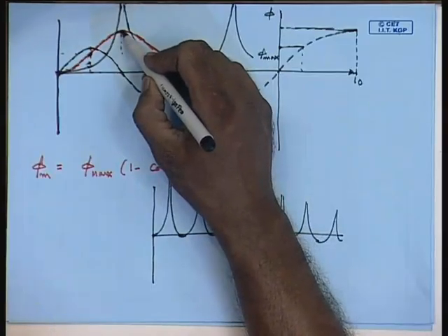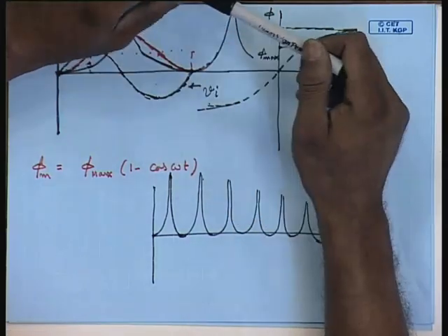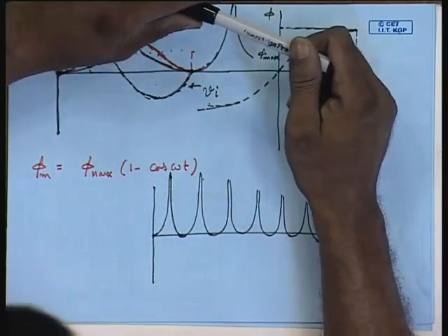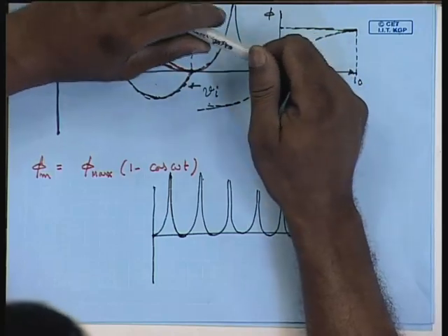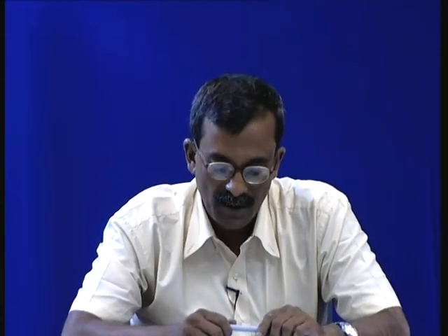So, if you have some remnant flux in the transformer, then the peak flux density may increase even more than twice the steady state peak flux, in which case the peak of the inrush current will also increase accordingly. On load though, this effect becomes somewhat less, because the flux decays fast and the peak value of the current reduces faster.